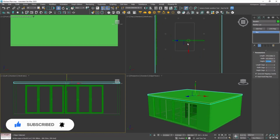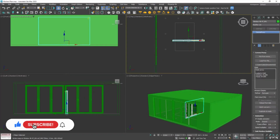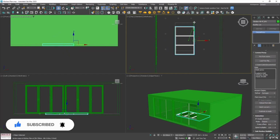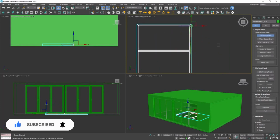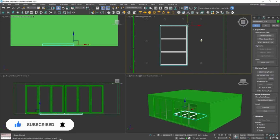So let's select our windows that we wanted to put in our roof. And let's rotate these by 90 degrees, and also 90 degrees this way. So we can move these in position using the snaps, but notice that we can't snap the top corner. So we're going to go to Hierarchy, Effect Pivot. And if we zoom in, we can snap this to the top right of our windows, turn off Effect Pivot, and this will now snap to our floor plans.